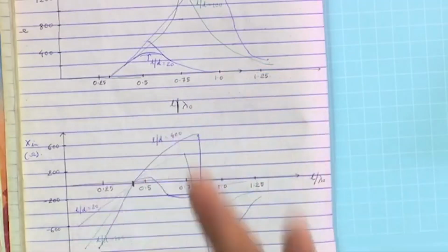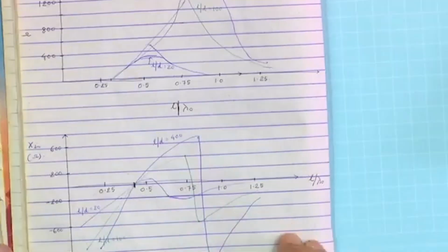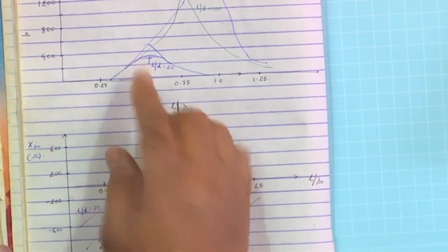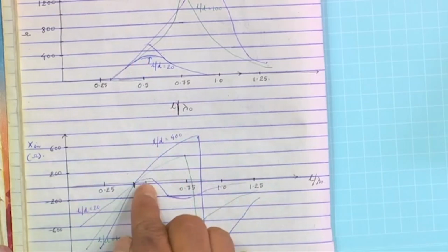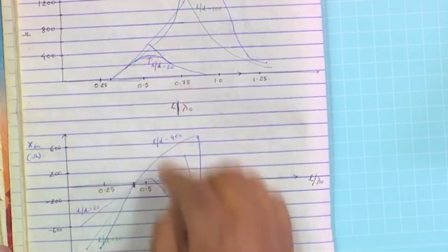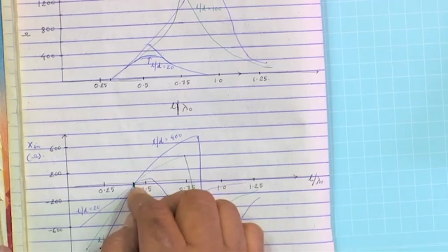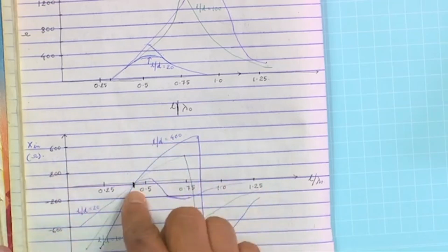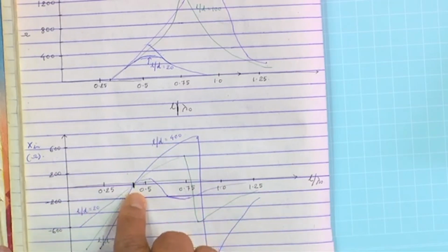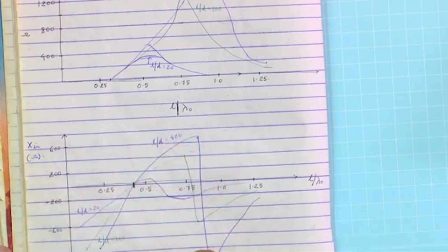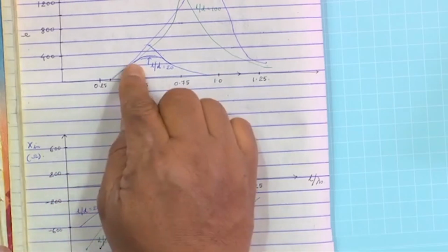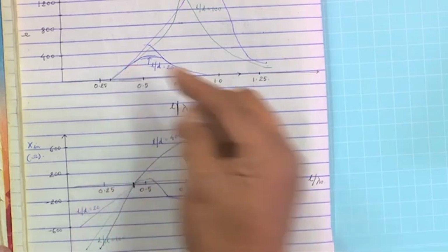That makes the resistance shoot up, and that is why it is a problem there. But near 0.5 we have a good resonant point. If we make it 0.48, then we can have a perfect resonance, and there the radiation resistance is also quite sizable.